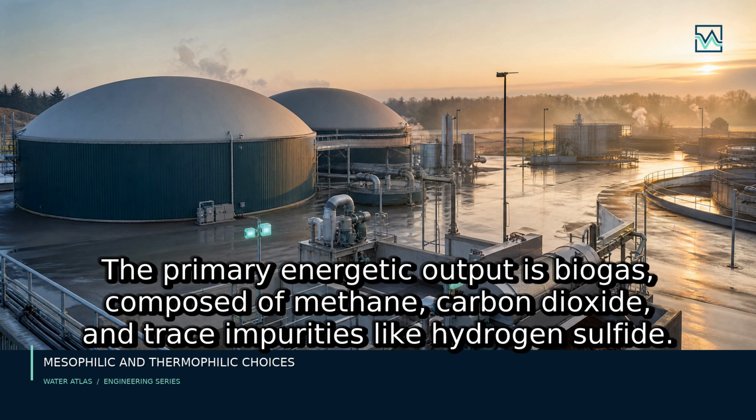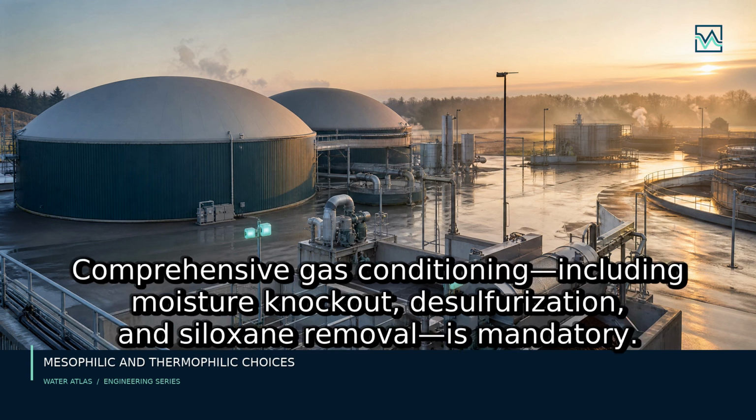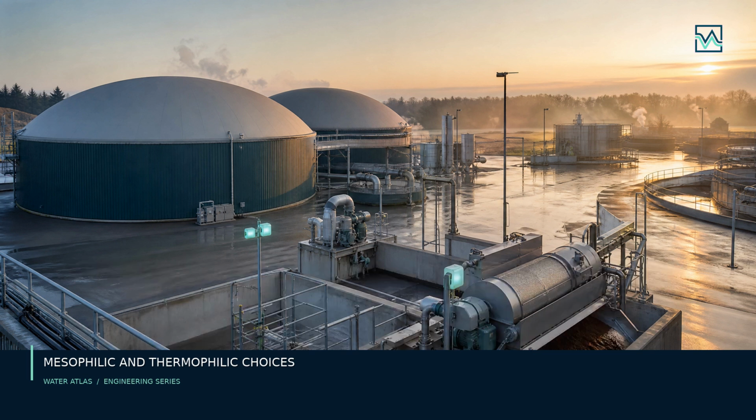Ensuring long-term stability in an anaerobic digester requires continuous monitoring of core process control variables. Operators rely on a suite of physical, chemical, and biological parameters to detect early signs of operational stress long before catastrophic failure occurs. The primary telemetry parameters include digester temperature, hydraulic and organic loading rates, solids retention time, biogas production volume, and methane composition. Chemically, reactor pH must be maintained within a strict neutral window between 6.8 and 7.2. However, pH alone is a lagging indicator. By the time pH drops, severe acidification has already occurred.